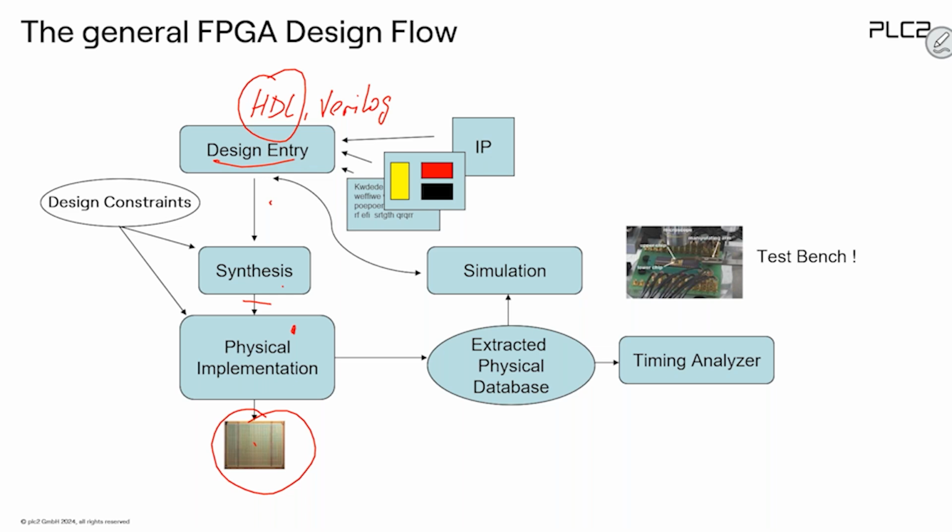And then what you can do, this is a very nice option, of course. It's also a webinar which I will do, I think, in July. Before we actually go to the synthesis, we would like to understand, is what I'm doing correct? Is it really correct? Then we will run a functional simulation, just the function, no performance, no timing, because this is just theoretical. This is just source code, okay? So the function is there, but not the timing, for example.